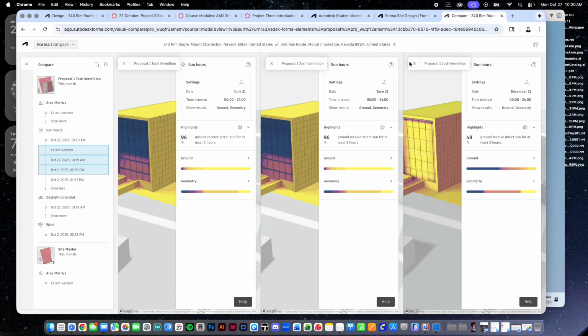And December 21st, when that sun is lower, then of course this little inset is not providing much shade on the south side, right? So we're being pounded with the sun. So we can begin to understand just how well our shading devices are working or not working, and again, start to craft deliberate and useful strategies then for mitigating things like glare, heat gain, etc., right?